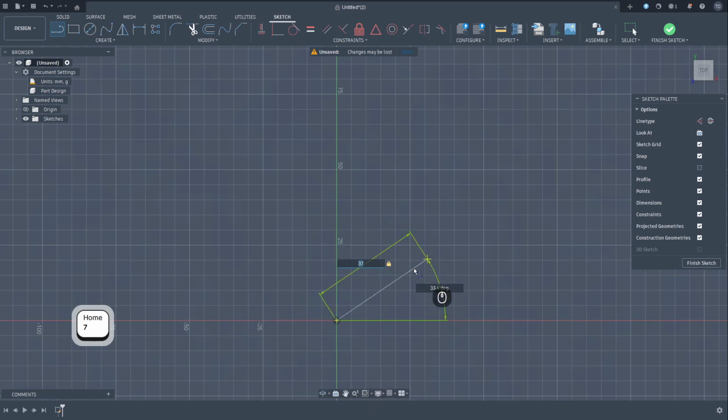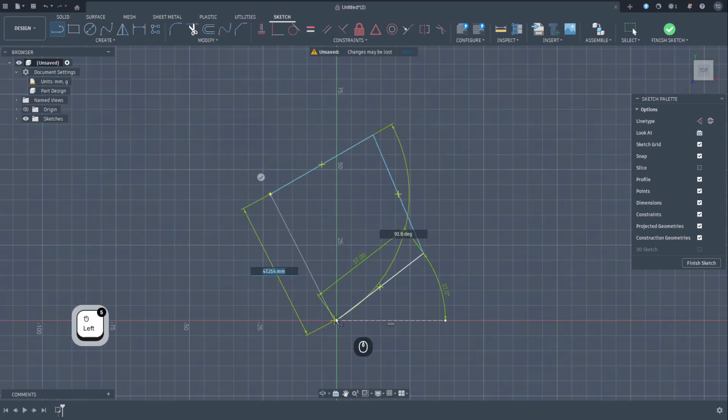So that's how you make a line that is a certain dimension and a certain angle towards your starting point. So let's say you want an angle of 37 degrees as well. Tab on our keyboard and you can switch to your degrees, and there you just type 37 degrees, and that's your 37 degrees line at 37 millimeters length. And that's a simple line to create, and just by adding and stacking other lines, you just create shapes from that.